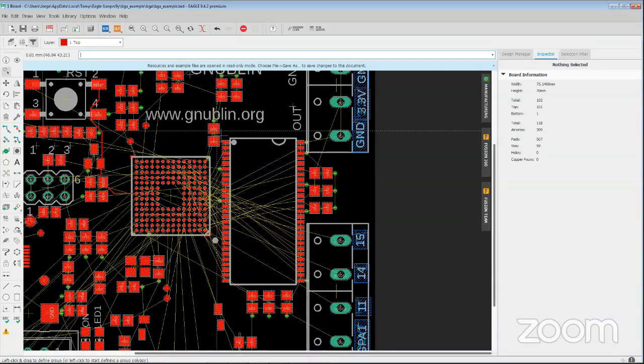It's a great tool, and don't get me wrong, we're not knocking it because it's extremely powerful, and a lot of things were considered to implement into that algorithm, and it does a fabulous job. It's just always consider trying to do your manual routing. You're going to get a much nicer looking board, commonly aesthetically correct. It also lets you be in much better control when you go back to troubleshooting. We understand that the auto router is tempting to get the project done faster, but there are so many factors to take into consideration. So use it as part of the tool, not the tool.